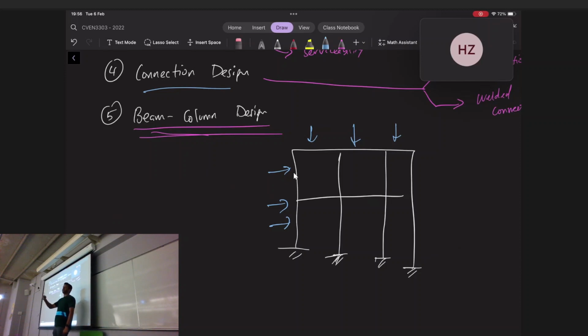Then you've got to see, all right, so it works for bending, it works for compression. Will it work if they both happen at the same time? Then there's another formula that checks combined behavior when it happens at the same time. Okay, and there's a few other things, and then probably to check this for compression, you'll probably end up using gamma method as well.